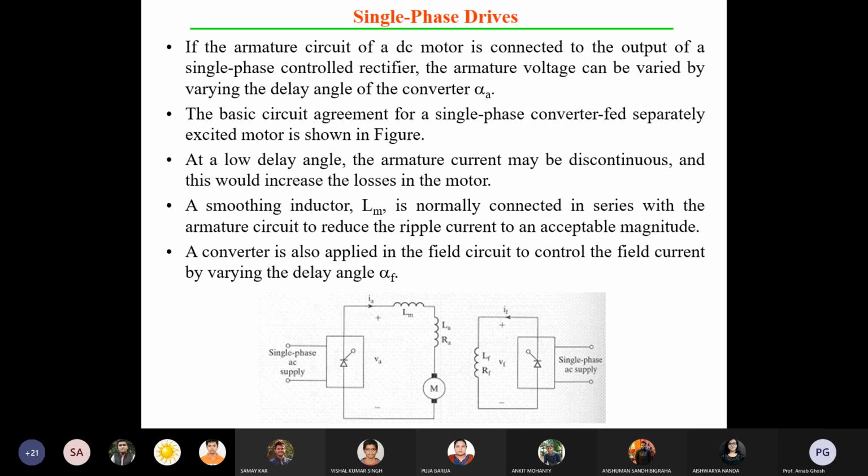The body, the wheel of the locomotive, and the railway track form the return path. So single phase AC is available as the source. And what are the traction motor types? They are DC motors, normally DC series motors. So we have to convert that AC to DC.